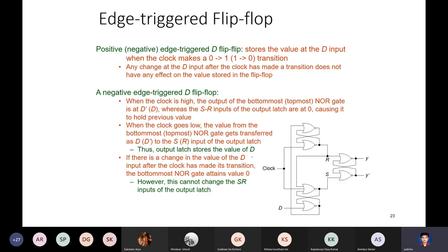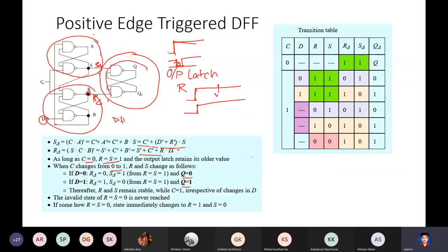Okay, so with this I kind of end this. Next class we'll go into design of more complex circuits. So we have studied basic latches, 4 types. Then with an enabling input, where we put a clock, it's a clocked latch, which we call a flip-flop. We can have further circuits to overcome the problems of stability and multiple changes in an enabling clock cycle by having either edge triggering or master-slave combination.